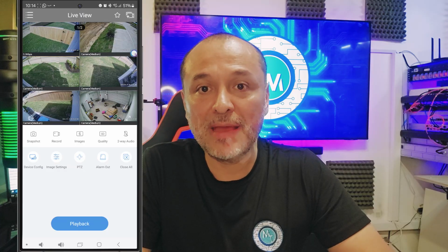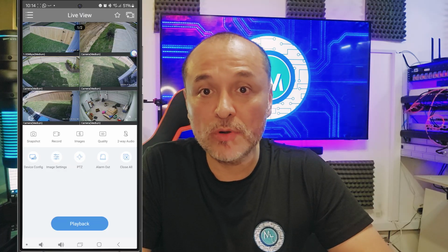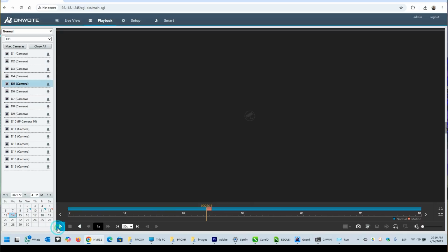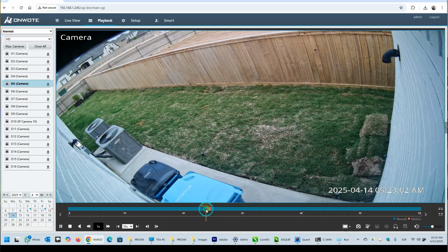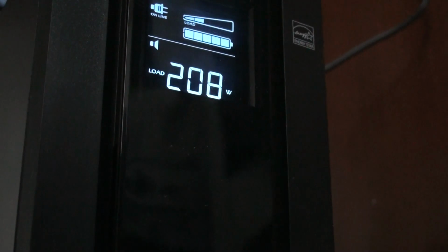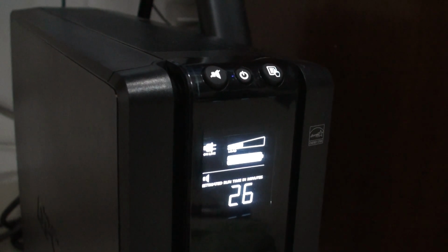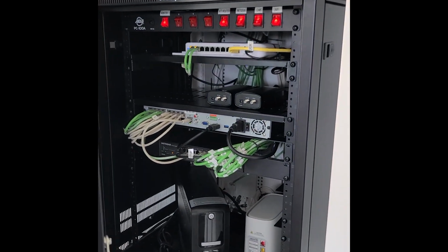The hard drive capacity will vary depending of course on the recording mode that we have configured. By default, it will record 24/7 on all channels, which is our recommendation especially for this type of systems so you don't miss any important events. Another recommendation, and very important indeed, add a UPS to your system so it will be protected from power outages, centralizing the power supply and keeping the system recording 24/7. Which will most likely require installing an additional hard drive to provide more recorded history.